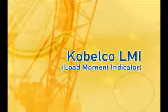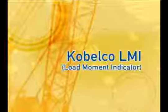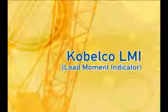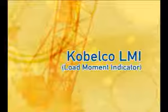In this section, we'll cover the Kobelco LMI, Load Moment Indicator. This is an operational safety device that is designed and built by Kobelco as an integral part of the crane's design. This system provides audio and visual signals as the load or the radius approaches maximum limits and stops crane functions when the limit is reached.